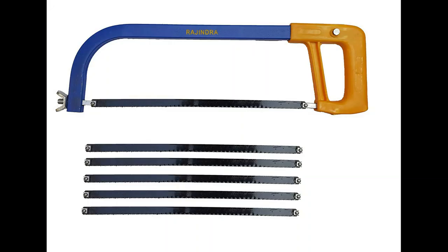The first tool that we will need is the hacksaw. With a hacksaw you can connect the blade using two pins, and there is one screw at the end. The hacksaw blades are always to be aligned forward so that it helps in cutting. If you align the blade teeth backward, it will not cut the wood. The more teeth per inch, the thinner the material it is used for.